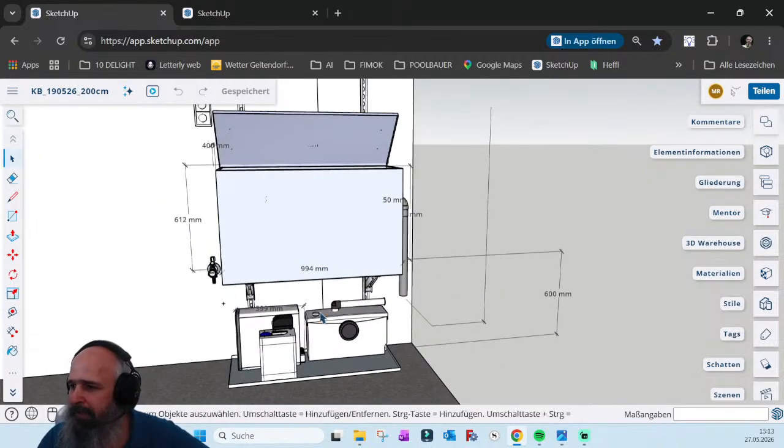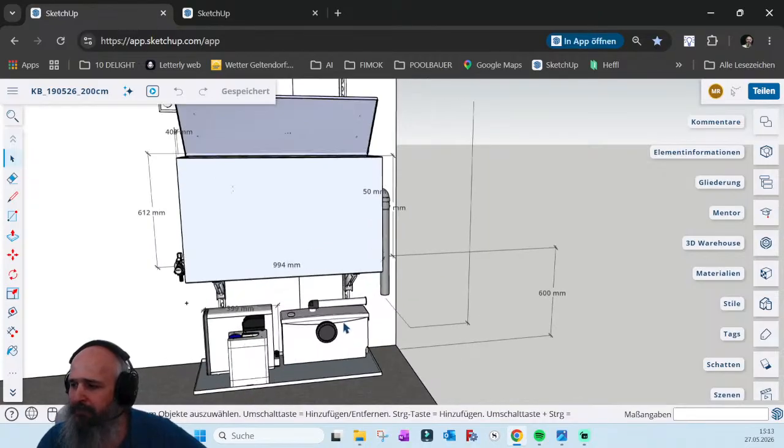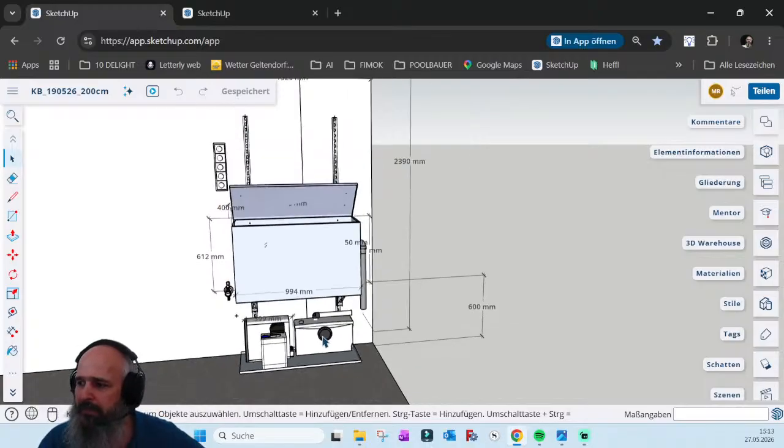And we also had the reverse osmosis, the metering unit, and water additive, and this lifting device for the wastewater, because we are below ground level, in a kind of ancient basement, and we cannot have the wastewater flow by gravity. So we have to use this, I don't know the English expression, but I guess you know what I mean, this pump where the wastewater is lifted to the gravity pipe